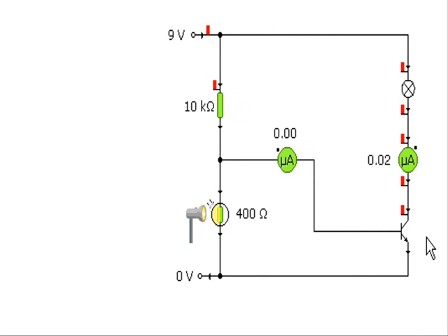The output driver we use in standard grade tech studies is the transistor. So we go in the light, the bulb is off. If we make it dark, you can see the bulb goes on. So we've got a current flowing in here of round about 0.7 milliamps, and the output here is 89 milliamps. So it's round about 100 times bigger. So the transistor is amplifying the current. The transistor is acting as a switch, and it's amplifying the current to be able to drive the output.